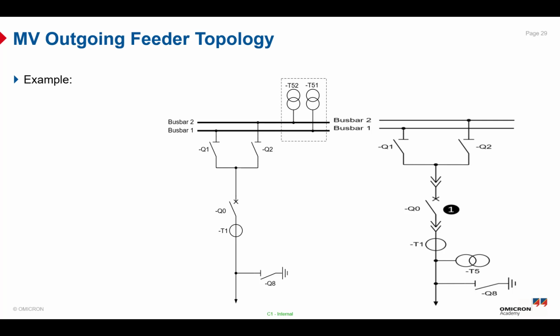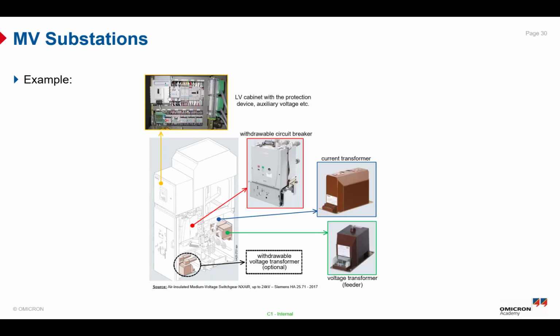So in summary, the main difference between the circuit breaker and the isolator is that the circuit breaker can break the fault and the load current with the arc quenching medium, but the disconnectors isolate the circuit but cannot interrupt the load or fault current. So the circuit breakers are used for protection, and the disconnectors are used for isolation and for safety.